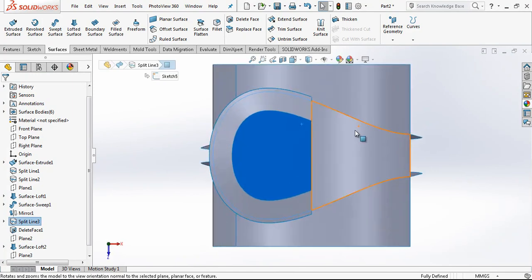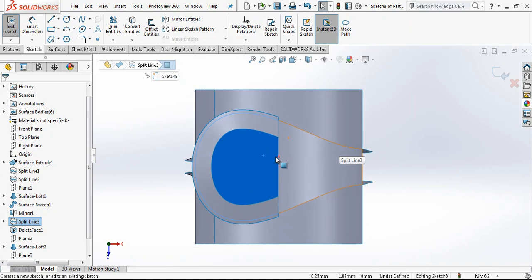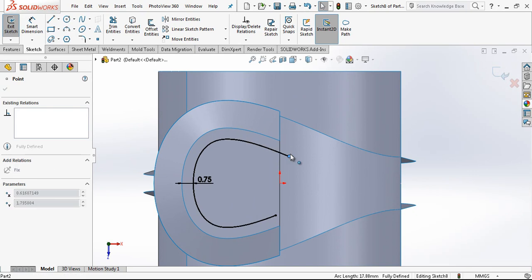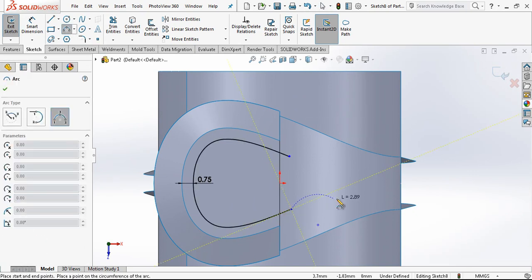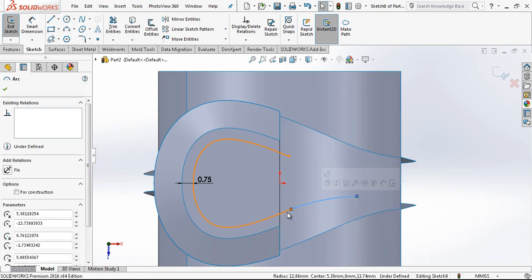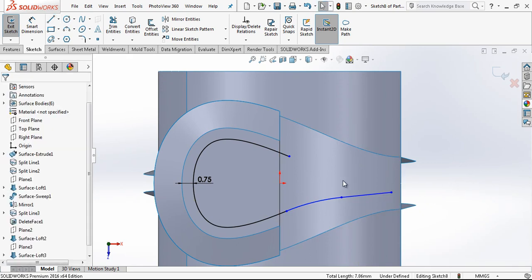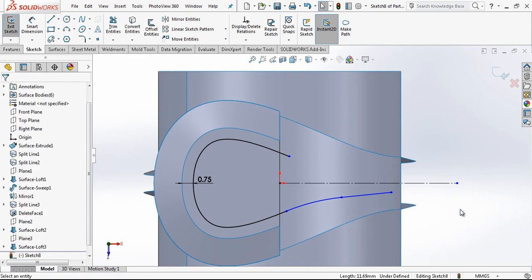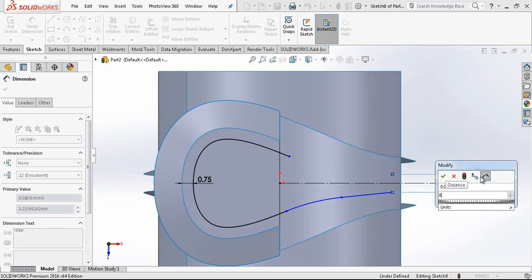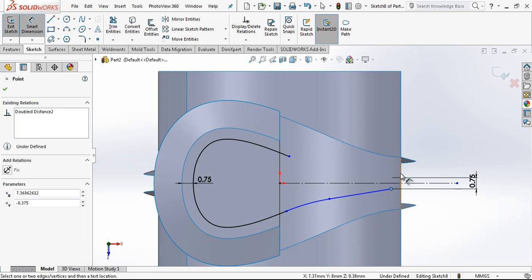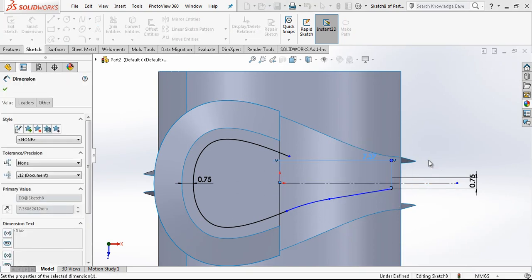Again we are looking at the surface. Here there will be an offset which is around 0.75 millimeter, and we are going to create here a radius arc, we can say, and that's going to be tangent to this point, and this dimension will be 0.75, and from this corner, from this surface, or we can just give from here 7.75 millimeter further.